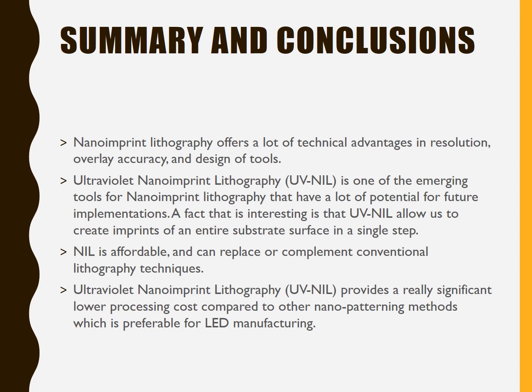As we discussed in this presentation, for photonics and optics, UV-NIL is the future in terms of lithography. Nanoimprint lithography is affordable and can replace or complement conventional lithography techniques. Even though it provides a significantly lower processing cost compared to other nanopatterning methods, which is preferable for LED manufacturing, for example.